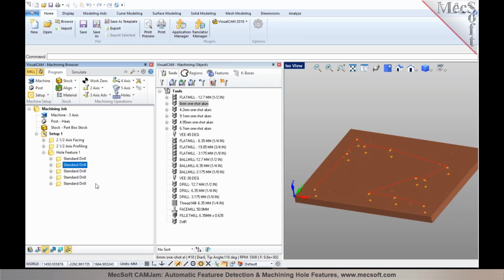So it'll look for a closest diameter tool that's equal to the diameter of the hole feature that you identified. If there's one that's closest to it, it'll automatically grab that one that's equal to the diameter of the hole. If not, it'll pick the next closest one which is equal to or less than the diameter. So you can see that automatically it selects the tool for it. So this makes your workflow a lot easier and a lot simpler.